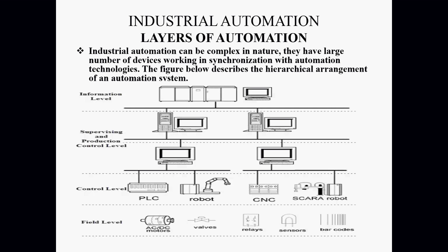But because of the supervisory control, I can witness that happening on my screen. And because I can witness it, I can take preventive and corrective action immediately. I can put my valve from auto to manual mode, and then I can immediately input an overriding manual command by which I can close the valve.